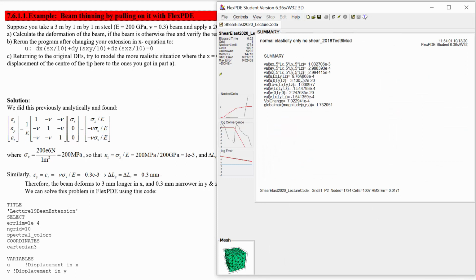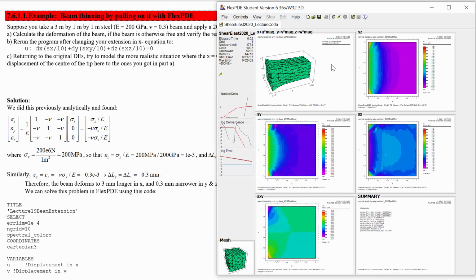So yeah, now compared to 1 millimeter, we've got about a 2.5% reduction in displacement compared to what we would have had if the anchor was allowing it to deform. So the anchors make, well, still not much difference when you have like a cube,